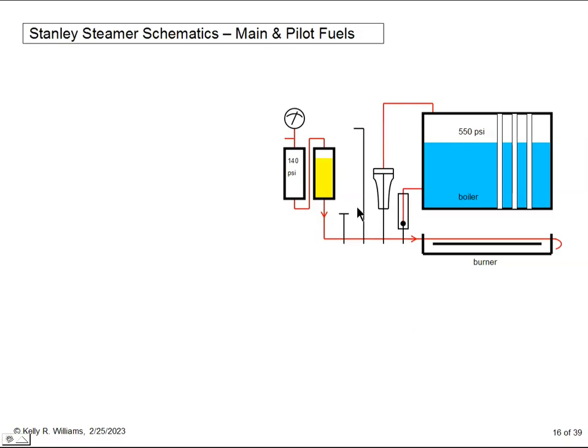Now, obviously, the fuel in the pressure tank has to be constantly replenished while the car is running. This small amount would only feed the burner for a few minutes. So the first thing we need is a supply tank that holds a lot more fuel. This is a good time to note that the use of the small pressure tank, which is a special Stanley feature, allows us to run the car with only a small amount of fuel pressurized. If there was some kind of uncontrolled fire, only a little bit of fuel could be forced into it. The main fuel tank is not under any pressure.